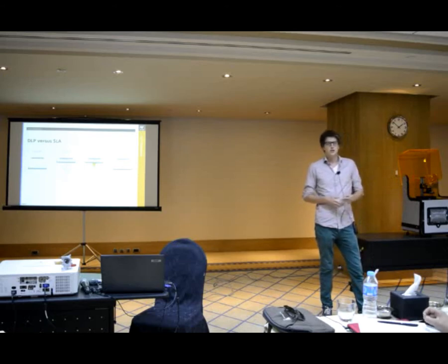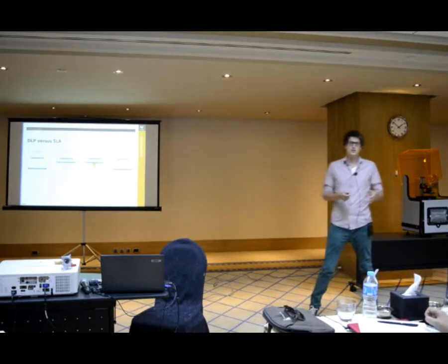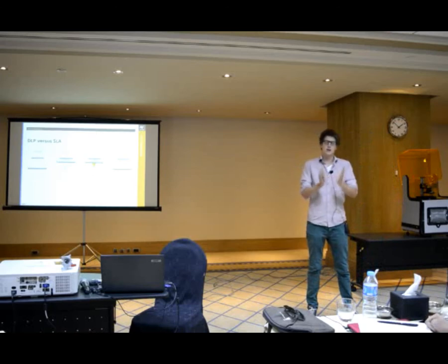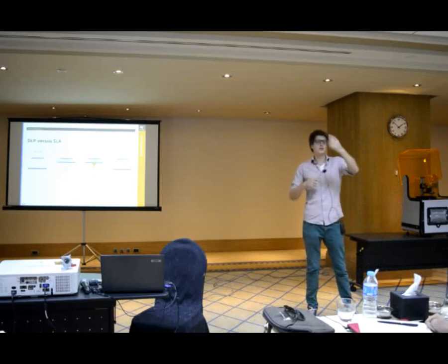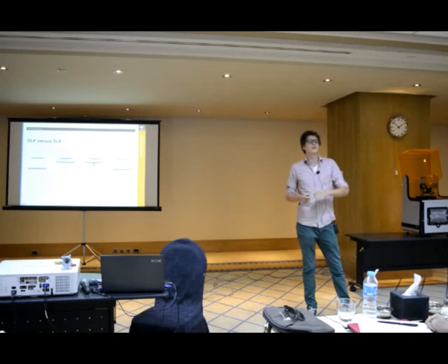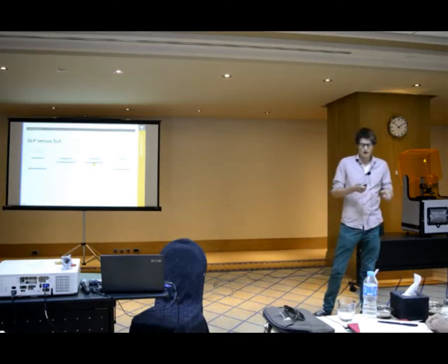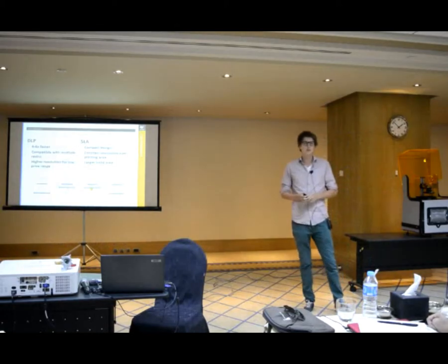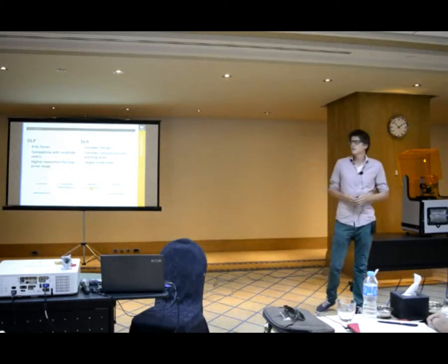Yes. On the other hand, DLP uses a projected image, so it can scan the entire 2D plane at once, and it uses a mask. So you have a light source, you use a mask which creates the pattern, and this pattern is projected on the 2D surface, and in that way you can project your 2D image as a whole at once. I will explain this in further detail later on, but I mainly want to show you the differences between DLP and SLA and the pros and cons.